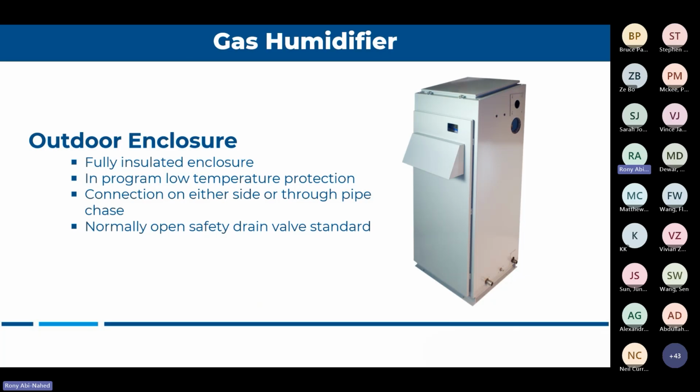So the safeties for an outdoor unit vary from brand to brand. Each brand has its own way to make sure that you don't freeze outside. But mostly what people do, you will heat trace everything that's outside. You need to heat trace it coming to the unit. When you choose an outdoor unit, the connections will be from the bottom of the unit.